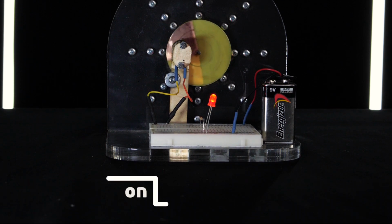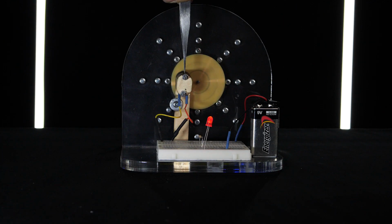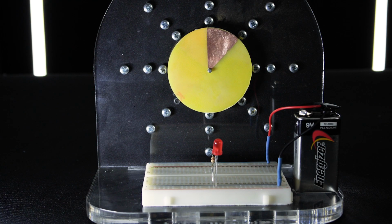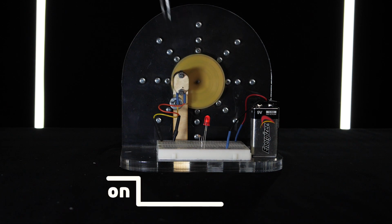Now it is only on for a quarter of a second and off for another 3 quarters. Wind up the disc. It looks like it is dimmer. Now install a disc that can conduct electricity with only an 1/8 part of it. Now spin it. The LED is barely glowing.